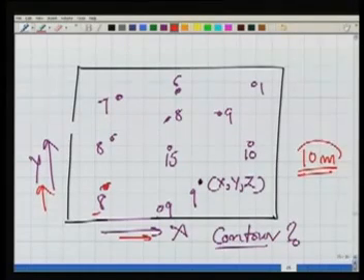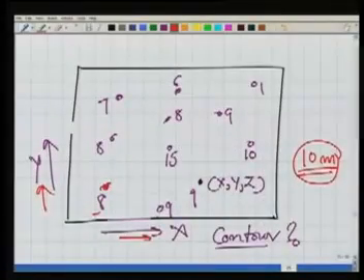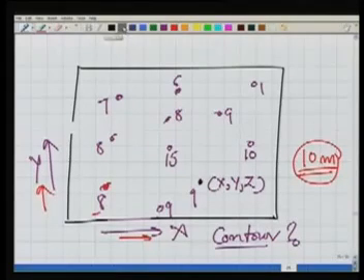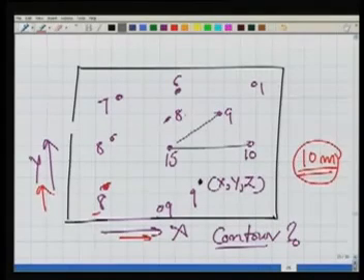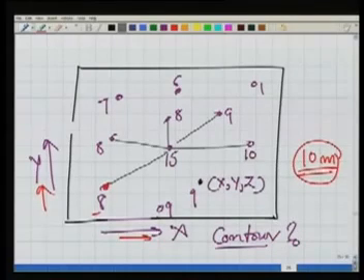We are interested in a contour of 10 meter. Now, where should this contour be? Well, generally the ground will have a particular kind of slope. Can we establish that slope? Can we establish that topography of the ground using the data which we have captured? If you look at that, a very simple procedure is that I can simply join, let us say, these points, all of them. I join these points. It's a very simple way.